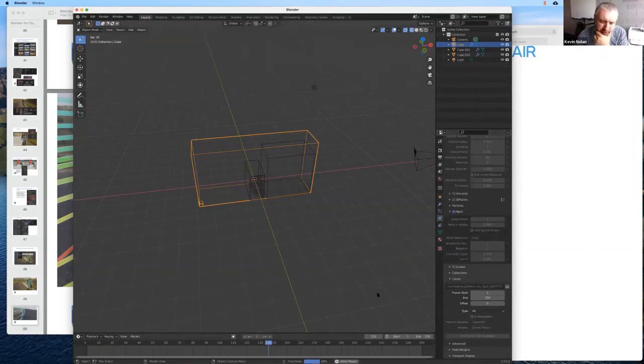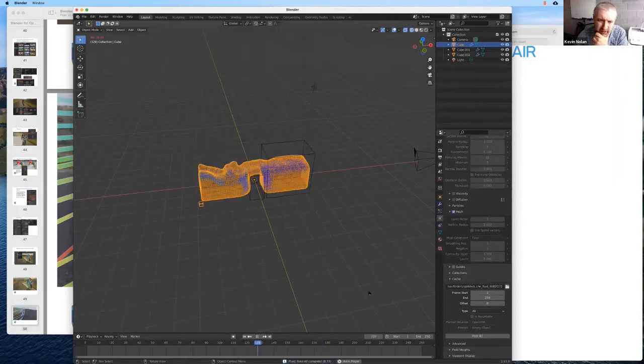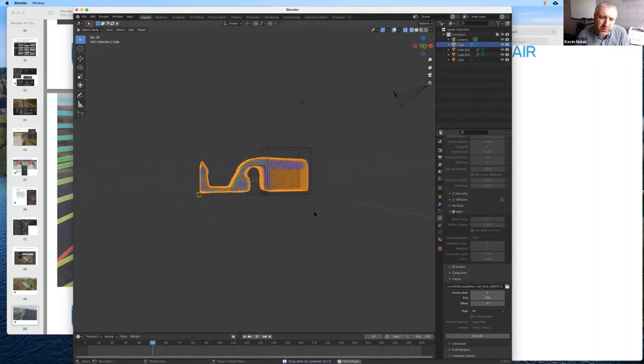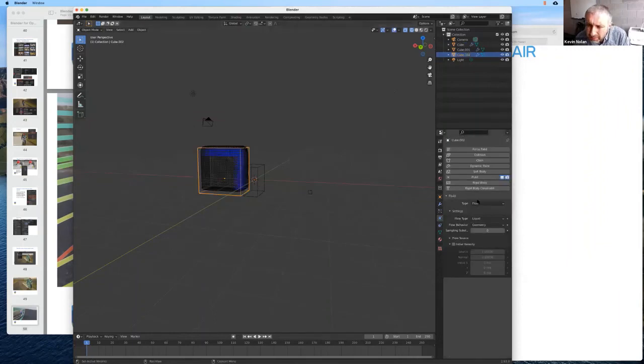So it's a quick and dirty way to create a fluid flow with very little effort. This is very, very nice. I've used this in the past to create some examples that demonstrate how viscosity works for free surfaces and things. It's a very nice way to create a simulation if you want to achieve something like that. My inflow here, you can see, is a type of flow, and it's a liquid geometry. It's a constant source, but you can turn that off. You can have it as just a simple volume of fluid as well.